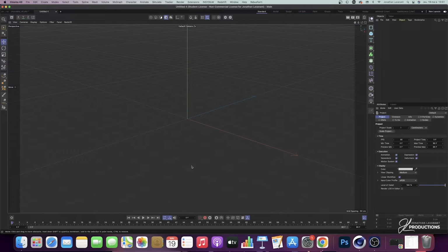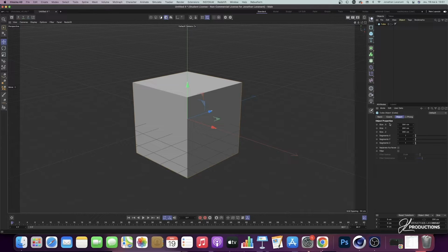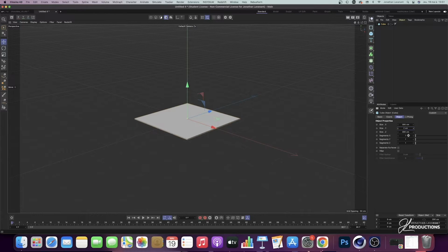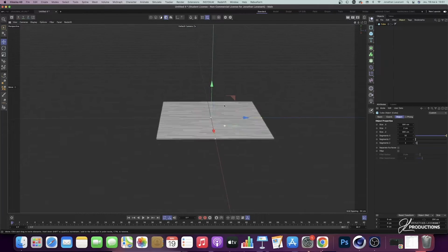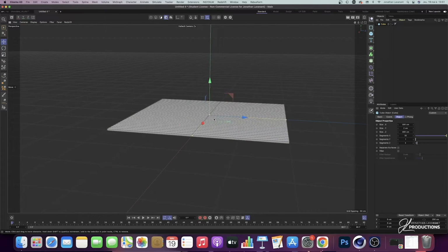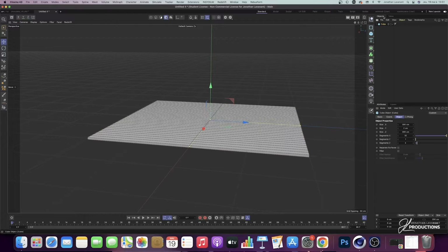So here, I opened a new window on Cinema4D, so the first thing to do is to add a primitive. I'm going to go to my objects level and add a cube. At the level of my object parameters, I'm going to add a 2 cm size at the y-axis level, and increase the subdivisions on x to 32 and the subdivisions on z to 2. And I will be able to put myself directly on display in quick shading lines to have access to these subdivisions right here. So once we've done that, I'm going to put this cube in editable mode.